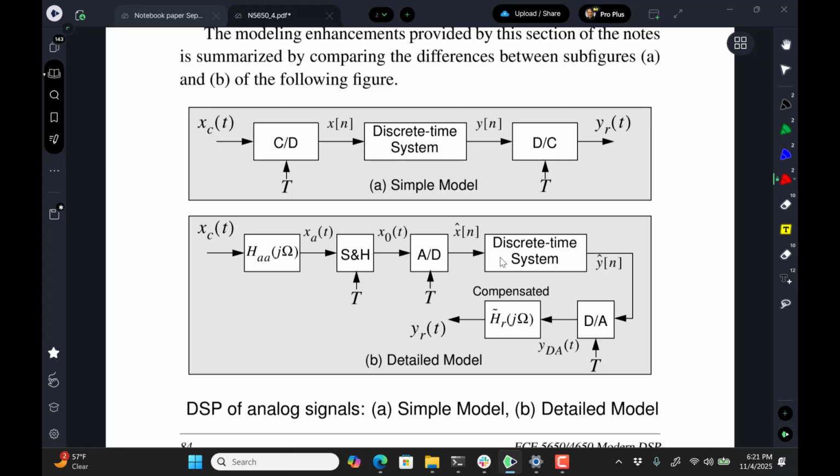Most of all this stuff kind of drops by the wayside, but we still have it hanging around. And then at the output side, we think of our D to A converter followed by an analog reconstruction filter. And you did see reconstruction filters last week in that demo of the 4x oversampling in the compact disc player. Remember that? We upsampled, and we're going to see that in more detail here for a more general case.